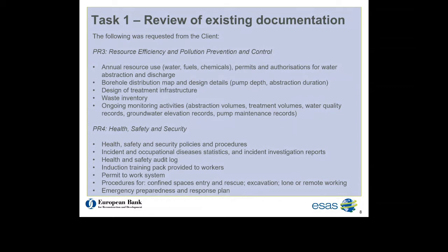We're asking for the borehole distribution map and the design details of the boreholes, such as their pump depth and their abstraction rates and durations, so we can start to appreciate where the water is coming from and from what depths and how well it's being monitored. We're also looking for information on the design of their treatment infrastructure, so we can understand what the likely discharges are from that infrastructure.